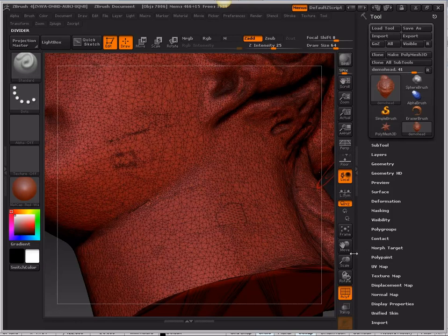Now these retopology tools were created by ZBrush to clear this up so the ZBrush tools work better. And again, the side benefit is it also benefits us in T-Splines. Any procedural tools that you run across an area where the topology is inconsistent, your tools are going to give you inconsistent results.